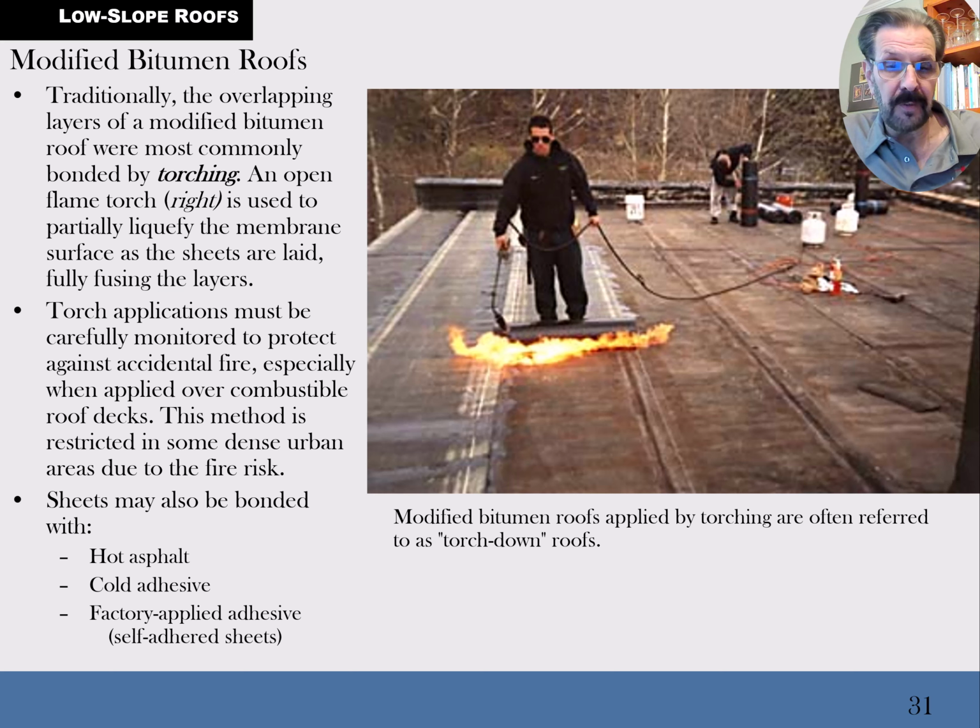The problem is buildings have been known to burn down from this. Wonder why? Look at all those flames. So you get an old house, and if any amount of flame gets into the inside of the building from this process, you could have a smoldering going on inside the attic that burns the house down overnight, or the building down. So torch down roofing is outlawed in some cities because they've had blocks of buildings burning down because of this. And it comes when everybody's asleep in the middle of the night, so it can be dangerous and kill people. So it's dangerous in several ways.